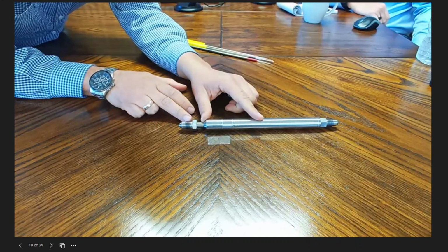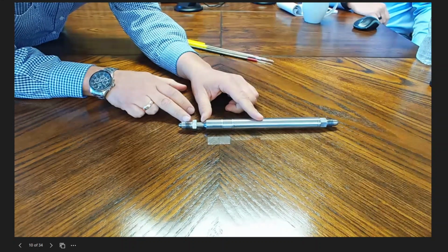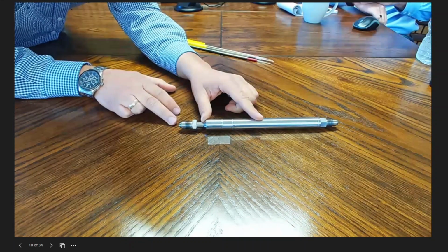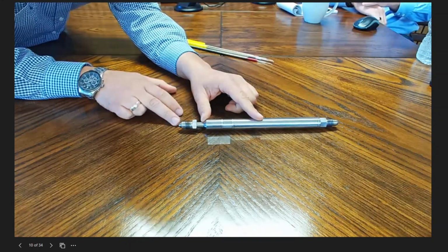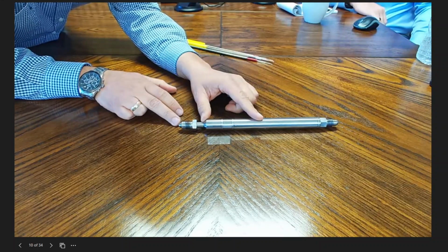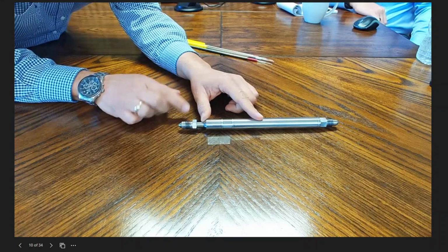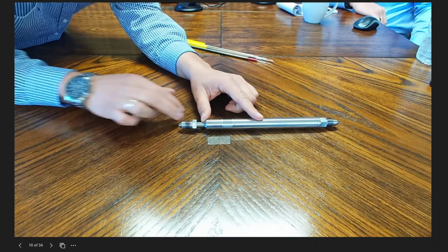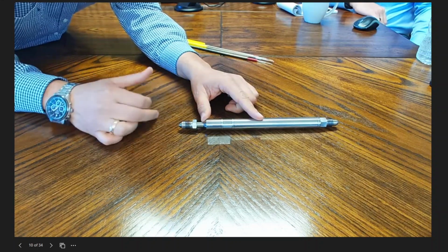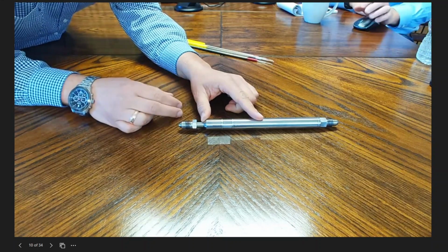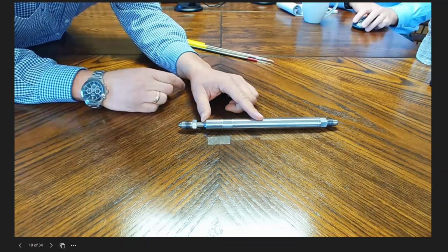If you're going to do tubing sensing measurement, you don't need the annular adapter. You just run it straight to the gauge carrier. If you want to do annular sensing, then you use the adapter in the middle between the gauge carrier and the gauge, and you can sense the annular pressure.